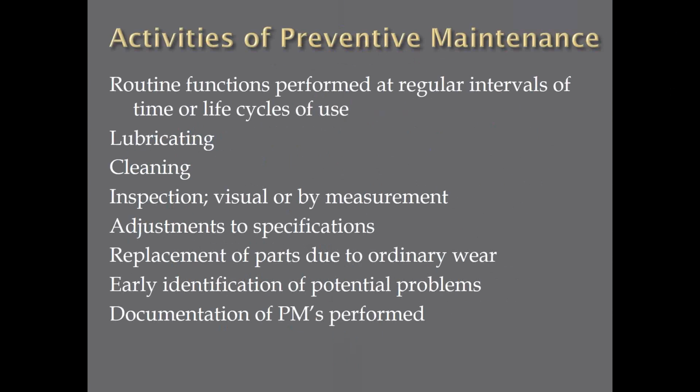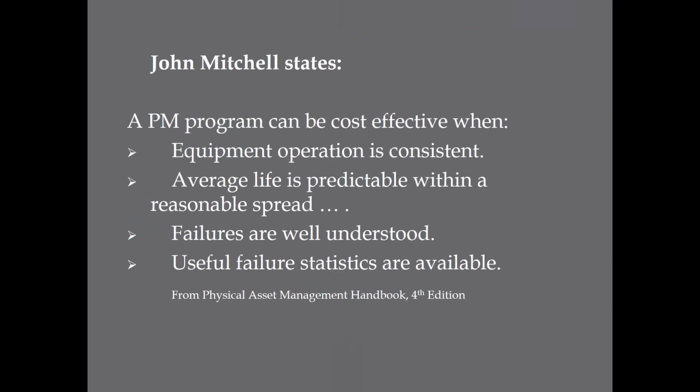And then the last one, a key. How do you document the PMs you perform? Is it just a checkbox that says I did it? Or are you putting some information along with that to say that you've done the task correctly and what you found? So those are activities.